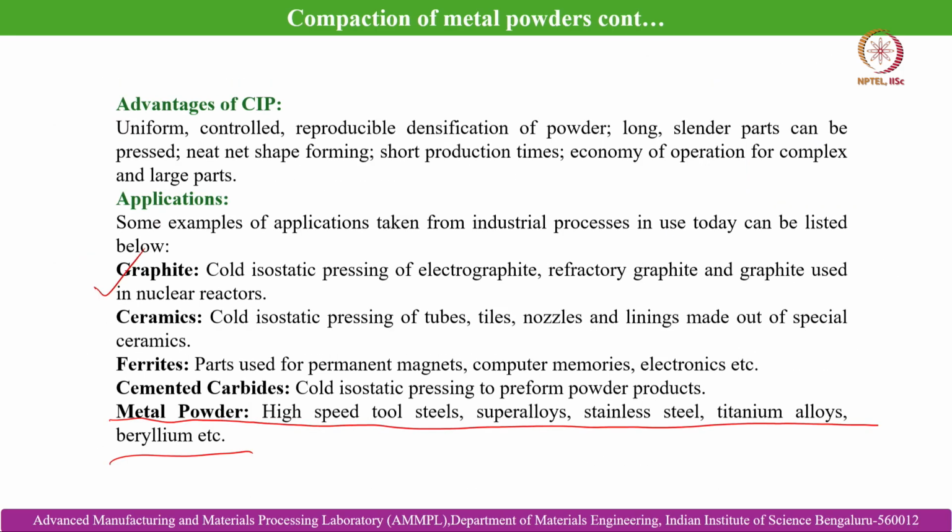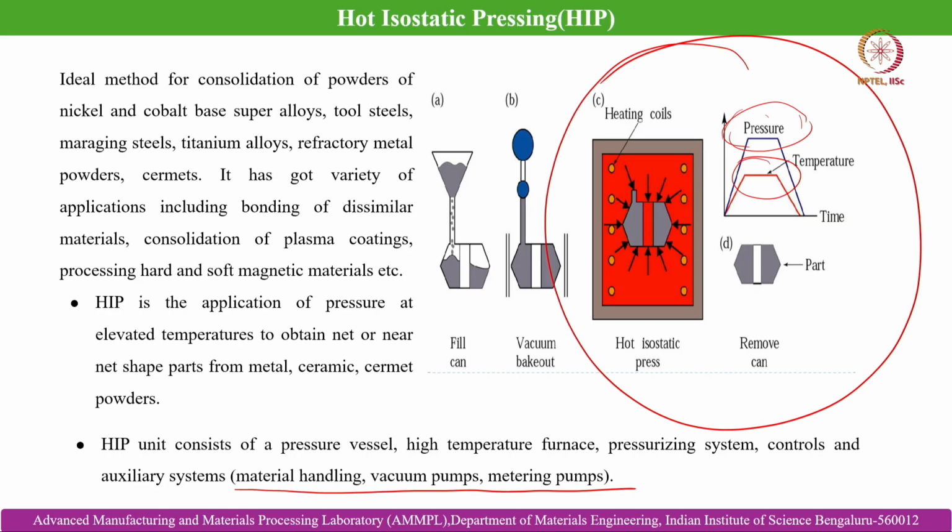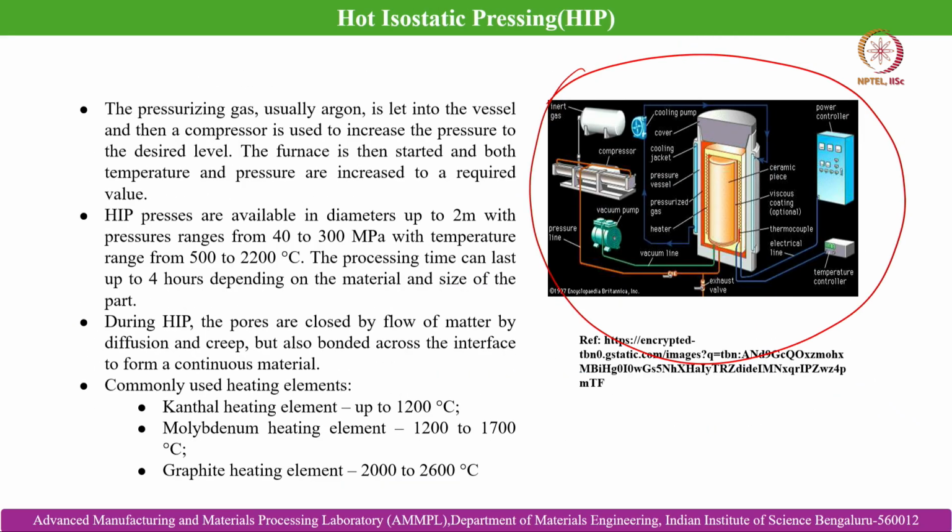In this case the applied pressure is limited to 300 MPa, which is lesser than what we generally exert in cold isostatic pressing, which goes beyond 500 MPa.